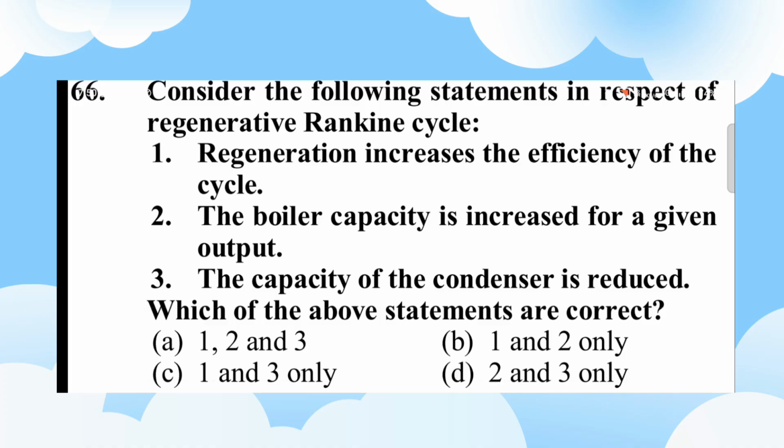Question number 66. Consider the following statements in respect of the regenerative Rankine cycle. 1. Regeneration increases the efficiency of the cycle. Yes. 2. The boiler capacity is increased for a given output. 3. The capacity of the condenser is reduced. तीनों ही करेक्ट हैं. Option A, 1, 2 and 3.